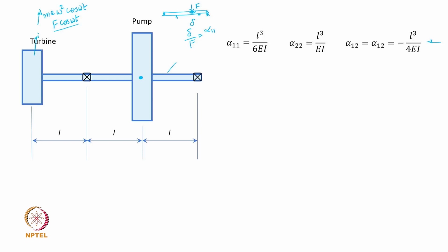You can as well consider the unbalance excitation or any harmonic excitation at the other mass, but that is going to be quite similar to what we have seen in the 2 degree of freedom, 2 mass system, where the response due to one excitation you can add up algebraically to the excitation from the other mass by appropriately accounting for the phase between the two, if there is a phase. And obviously there will be a phase difference of the excitation function here. Both excitations cannot always be in the same phase.